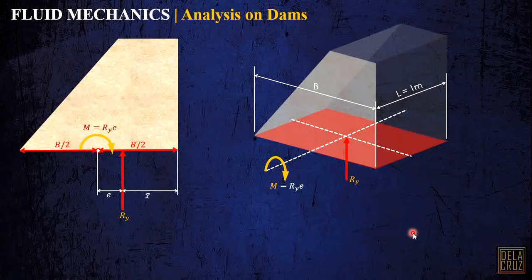Now, take note that from the strength of materials or the general principle of the stress, that is just force over area. No? Okay, that's why our stress in this area or the bearing stress is just force Ry over the area. And gagawin natin siyang negative since that is a compressive force na for the soil. No? Negative Ry over the area, that is the length times B.